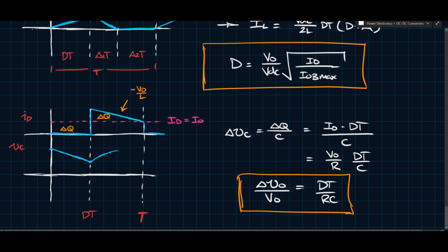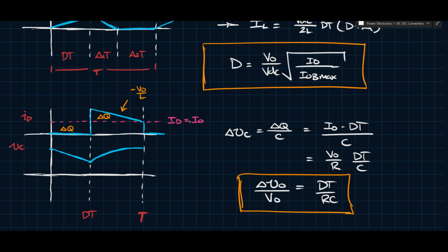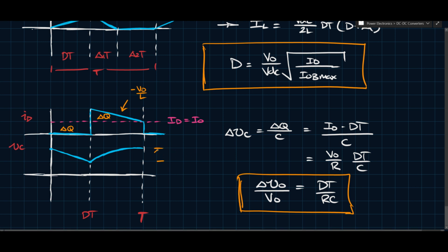And when capacitors charge, the current and the voltage of the capacitor are related through a sort of time derivative relationship, meaning if this is a ramp, then this has to be a sort of parabola, I guess you can say. And so that's what you have for this case. And this is obviously what we're calling delta V. Well, delta VO, I guess, or delta VC. I can say delta VO equals delta VC, just to be consistent with everything else.